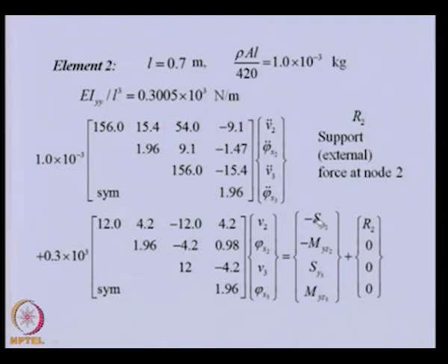If we join the two shafts, this will cancel because this is at the common node, but this will remain because this is coming from the bearing. So it is important to see how to handle the intermediate support: we need to add the reaction force from the support, which is unknown, as an external force, because it is not giving a moment. So it will not come here, it will come in the node 2 position only.